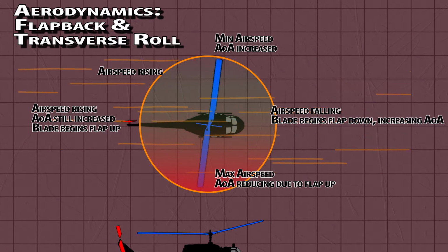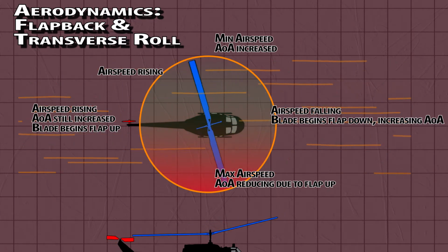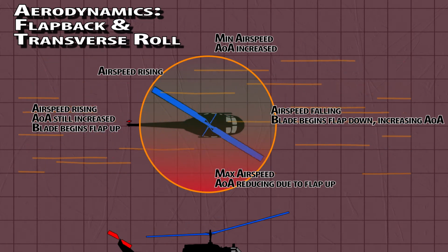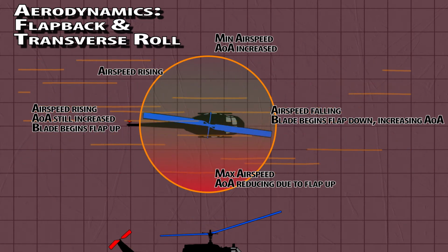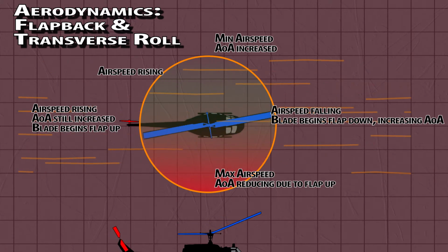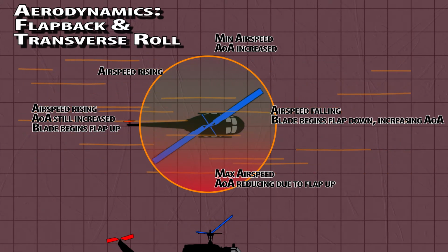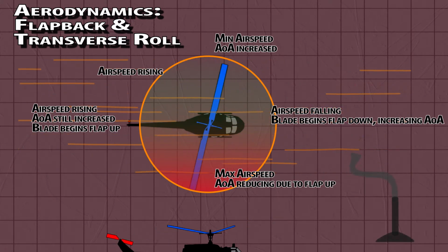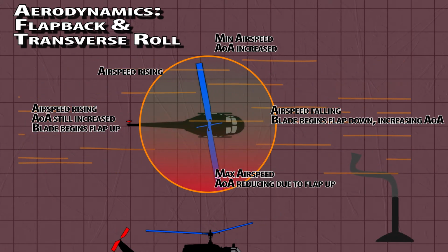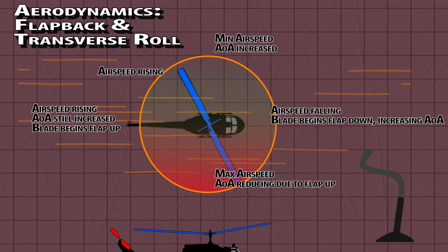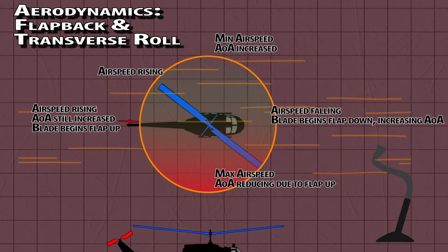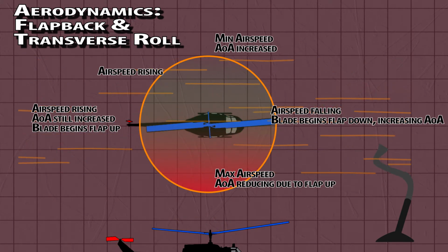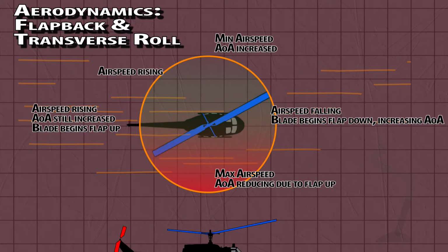We can see that the rotor will flap to equality, meaning it appears as if the rotor disc tilts as one unit, even though each rotor is just doing its own thing. This process results in a rotor disc tilt away from the wind direction without any input from the pilot. You will need to push the stick into the wind just to have a level rotor disc. As I said, this can happen as you transition from hover to forward flight. This will result in a forward stick motion to begin moving, then shortly after another forward stick motion to cancel